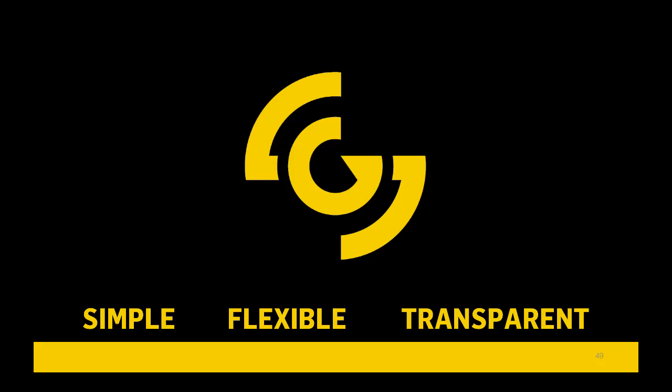Like I said, I usually draw the vehicle zones first, and then I look at whether there is anything that's going to affect the operation of that vehicle zone that I need to use an object mask for. And the object mask is not just for vehicle zones. For example, the camera may be mounted right above a white luminaire head, and in the middle of the afternoon, that whiteness is going to bounce back up into the camera, and we're going to use that whiteness to modify the white balance of the image. So you would use an object mask in that scenario to mask that out and prevent it from affecting the camera.